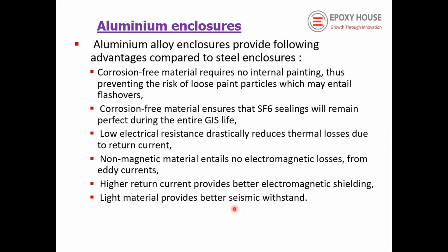Internally there is no paint as such. Some manufacturers use epoxy coating on the surfaces, but generally it is not used because loose paint particles could create a flashover. That is one of the reasons why they don't use it. And this corrosion free material ensures that the sealing will remain perfect during the entire GIS life.